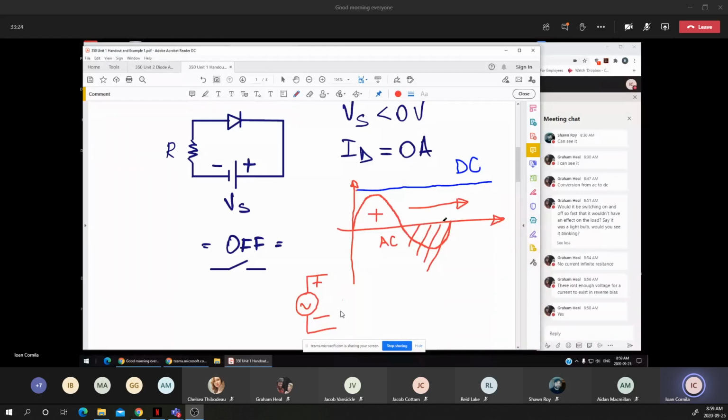That means the first part of having a rectified voltage is achieved. Again, it's the simplest rectifier, and it's called the half-wave rectifier. Now we may notice that half of the sine wave of the input voltage is rectified, and just half of the waveform is used over a full period of the sine wave.